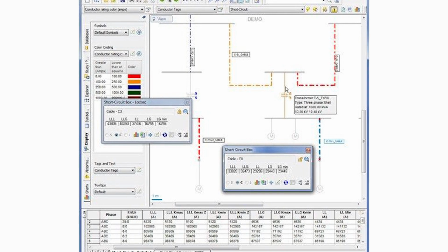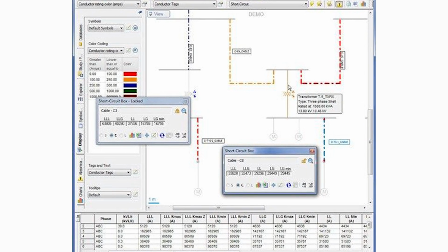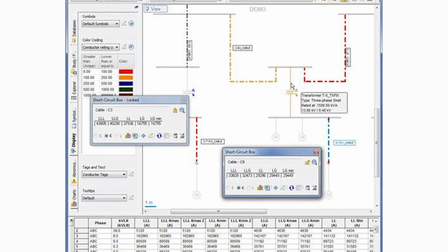The short circuit analysis will confirm that your equipment can actually interrupt that fault. It's not the 25 amp or 50 amp breaker. That's not the rating we're looking at. We're looking at the 10,000 amps interrupting rating on the breaker or on the device. So that's a short circuit analysis. It's ultimately required in an arc flash study to determine what all the fault values are going to be.